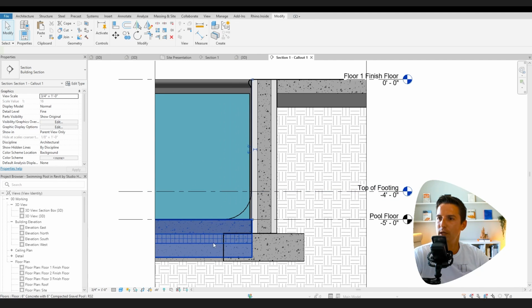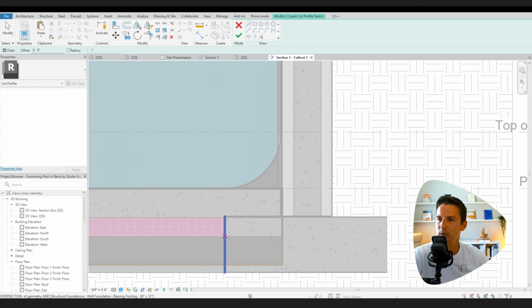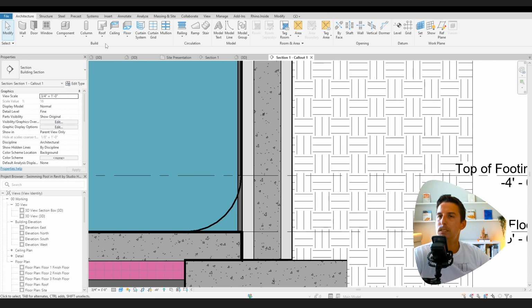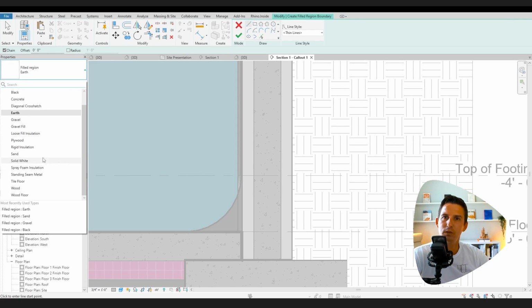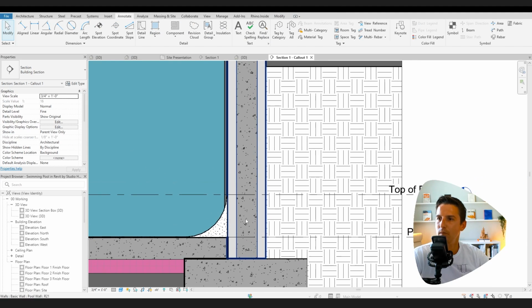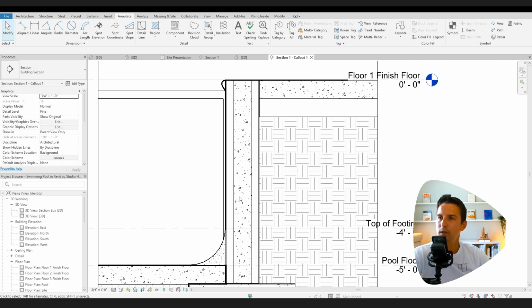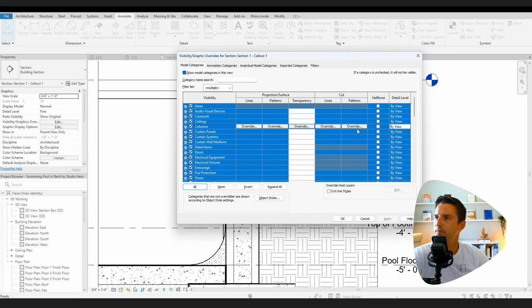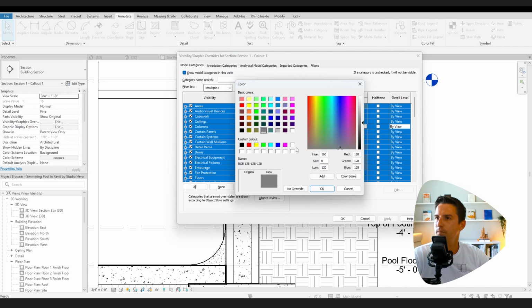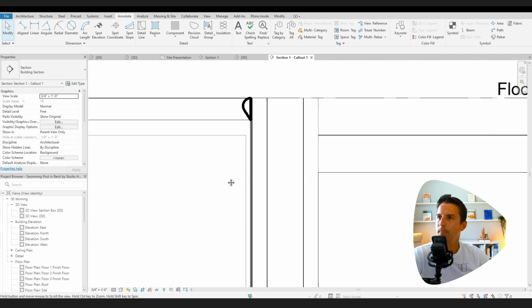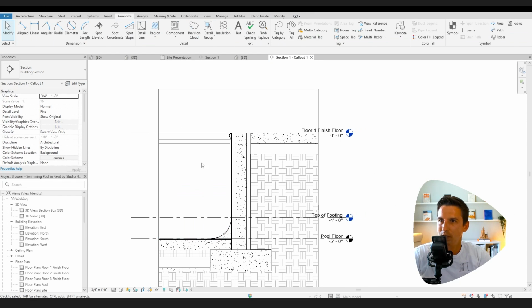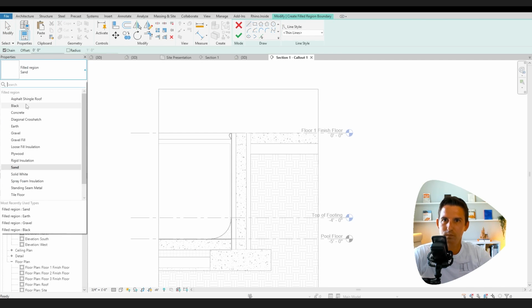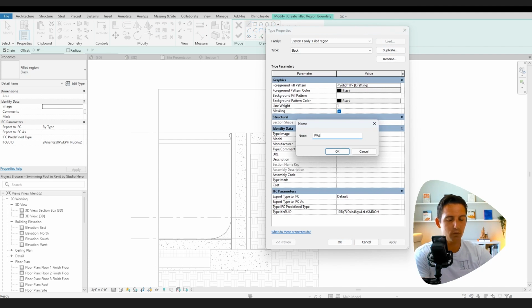All right. Now from here, we need to edit this to notch around how it's supposed to. It's under View, Cut Profile, do the bottom first. Annotate, filled region. Go to hidden line here. And I like to turn all the section lines to be thin lines. All right, so we have our water. Leave it like that for now. And we'll do a region, edit type, duplicate water.